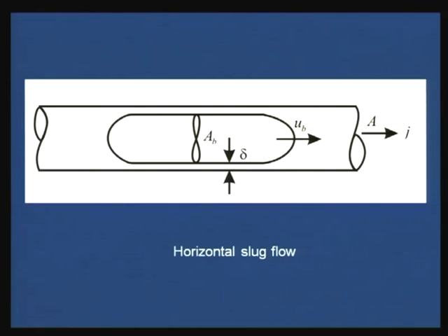Here we find that there is no drift flux due to buoyancy effects. Therefore, see, the entire analysis there was based on u infinity. Do you understand? What we did, we found out UG by J equals a constant, that UG was equal to U infinity. How did that U infinity come? Because the bubble used to rise in a vertical tube due to buoyancy. So, here the basic U infinity concept is not there at all, but UB is not equal to J. So, therefore, how to find out UB in this particular case? Let us see what we can do to find out UB.